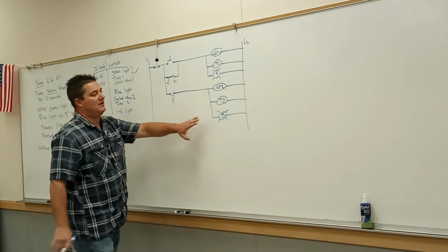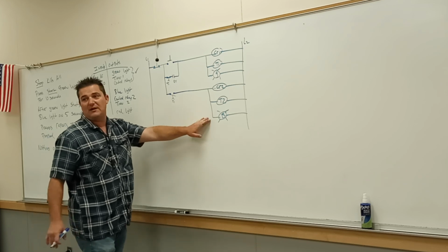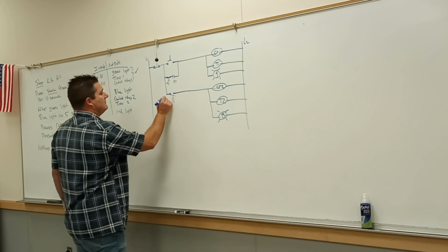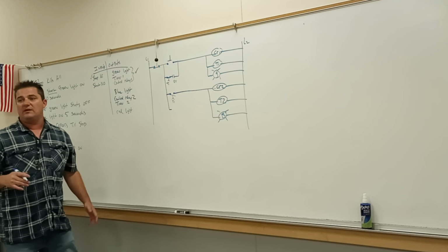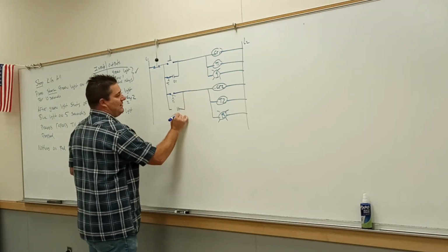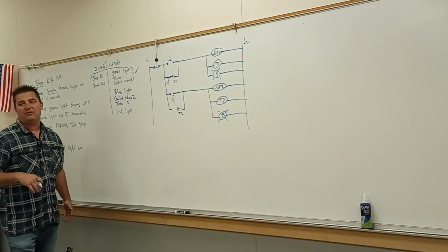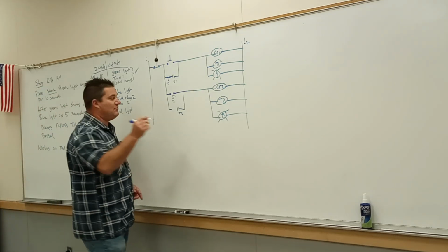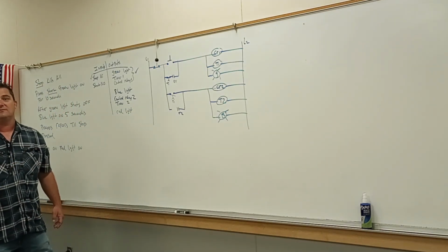To keep this on, you need to have what? If you want that blue light to stay on, what do you got to have? A memory circuit. Now, on my memory circuit, do I just need an open set of contacts like that? And we write CR2? Or is there something else I also need in that branch? Timer 2, specifically, do you want open contacts or closed contacts?